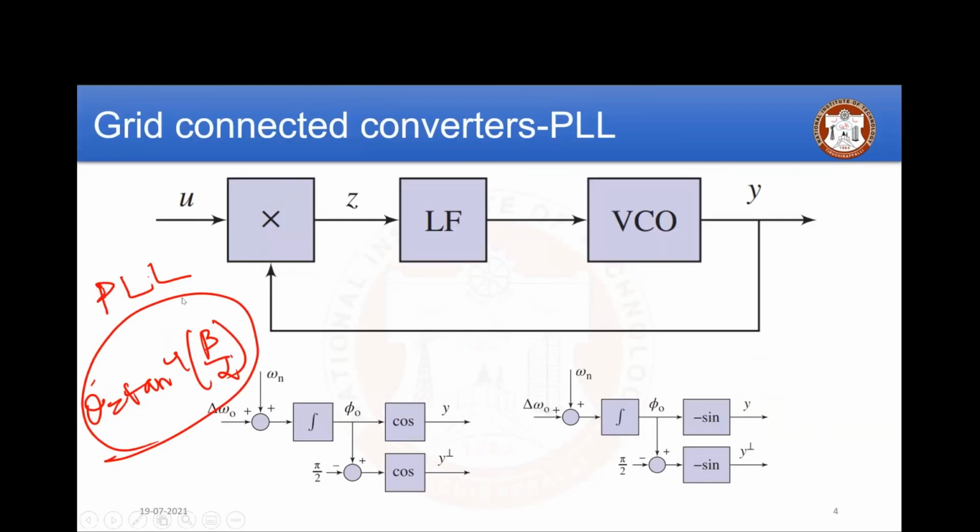But this is not a very good method because the theta representation is always a specific constant at a time, and it is dependent only on alpha beta magnitudes. Suppose there is any disturbance in VA, VB, VC, then the theta that was tracked may mislead your output. So this is not proper.